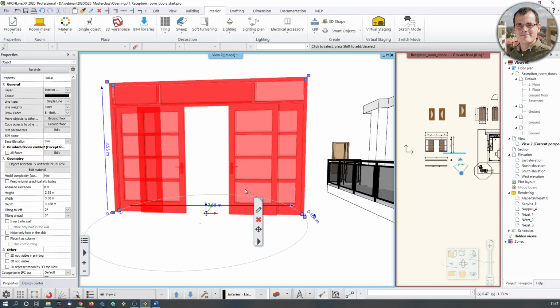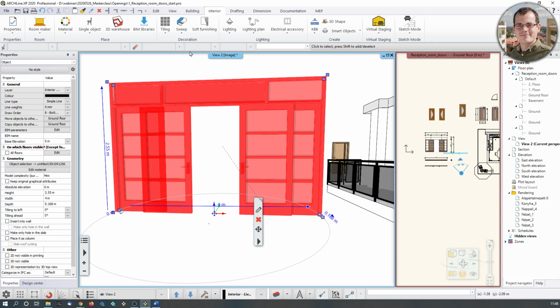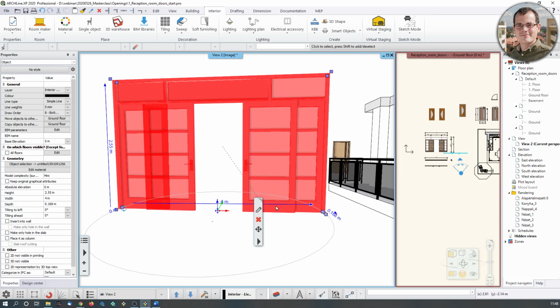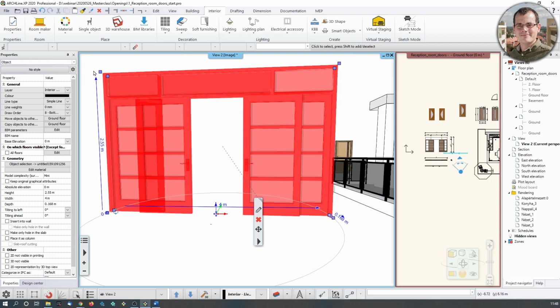We go back to the very basics now. When you want to resize something before you save it, you can do that. If you resize, let's say, this door into a 4 meter long, or in this case wide, door, you can do that, and the software tries its best to scale it. Now, when you are resizing something, how does the software know in which direction to make it larger? When you click on an element, you have two arrows, the blue vertical and horizontal ones, and they have arrowheads.